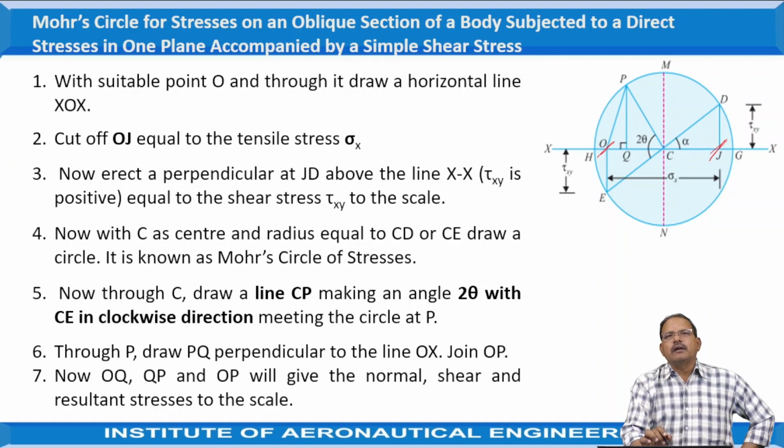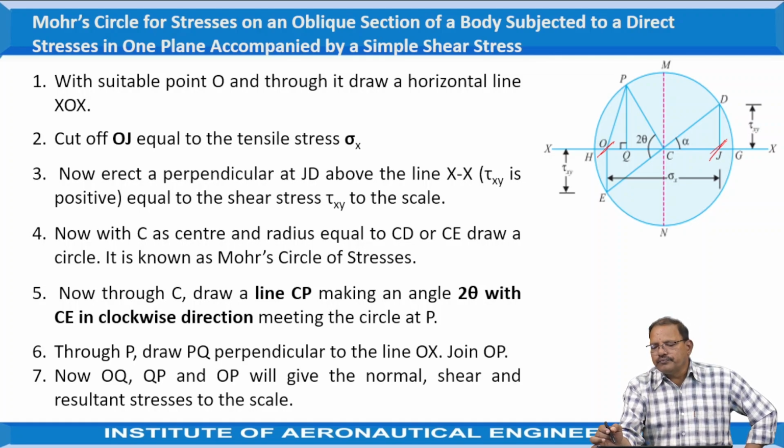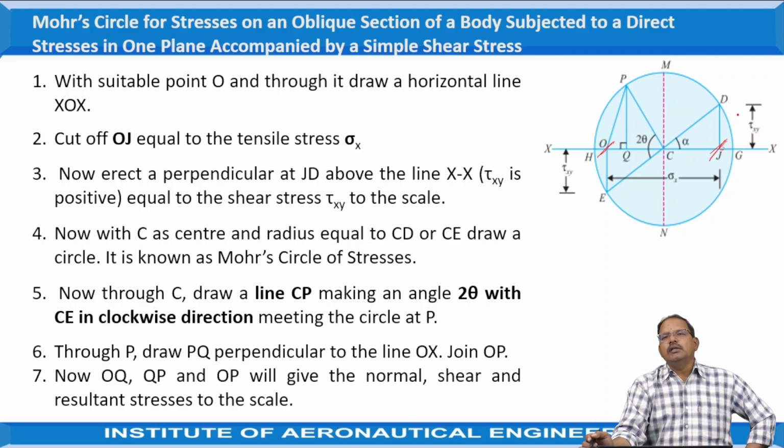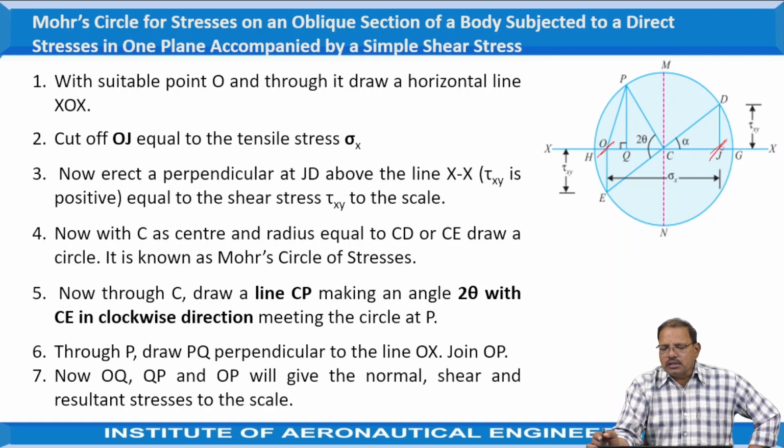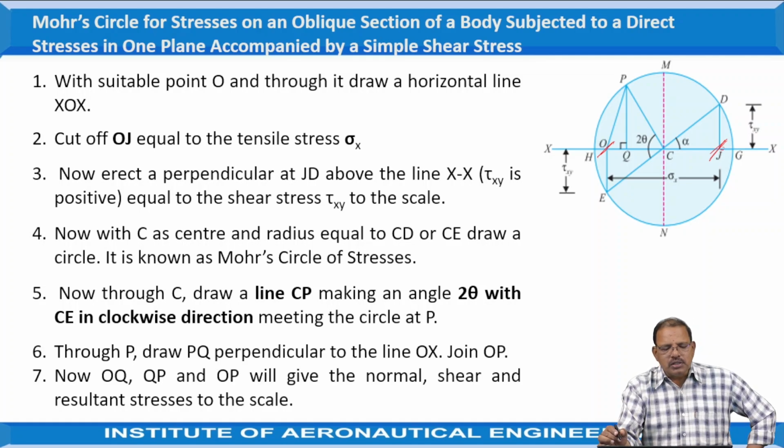Now erect a perpendicular at J, up to the point D, such that JD represents the tangential stress acting on the plane, according to a suitable scale.